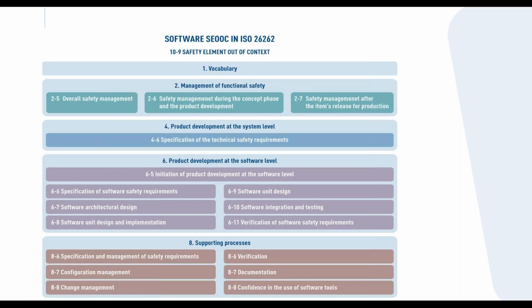And the specification really defines very well how you build up the safety element out of context, how you assess its suitability for use in that particular vehicle, how you integrate it, and how you verify its integration. And so 26262 was a development on from 61508. And to us, it's a really good starting point that makes it relatively easy. I hate to use the word easy in safety ever, but it makes it relatively easy to then use that in another environment like DO-178C or 62304, because all the elements you can consider for a software component are included within this standard.